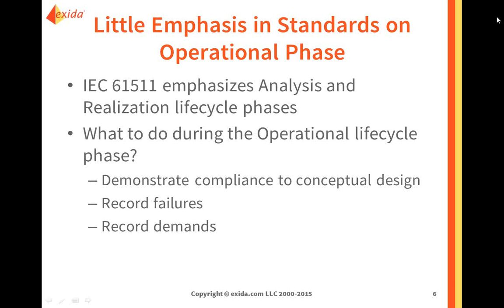So in order for that conceptual design to be valid, in order for us to be compliant to that conceptual design, we need to do these tests and any maintenance activities that are required. We also need to record failures. That's one of the things that the standards talk about. We need to record failures, and we need to record demands. Or maybe even better, we need to record the frequency at which initiating events occur.